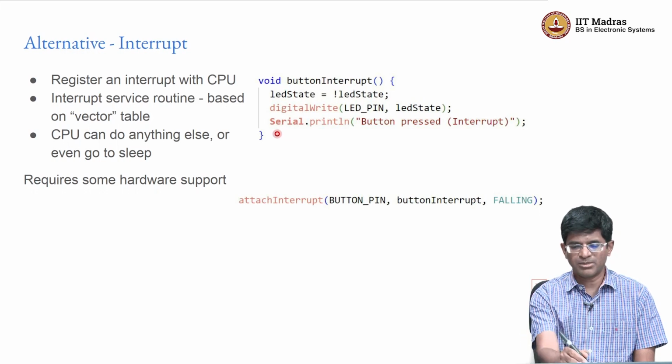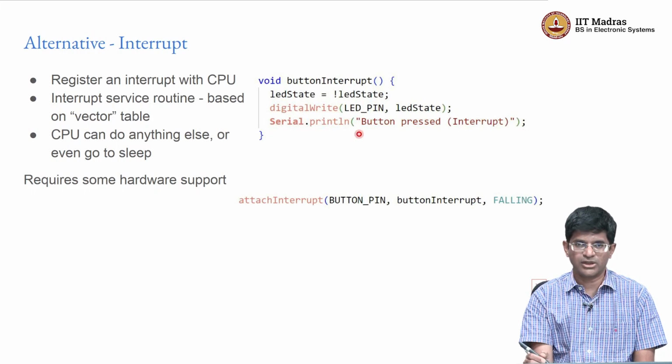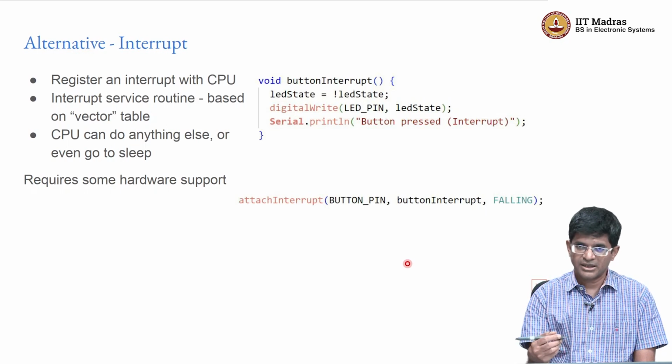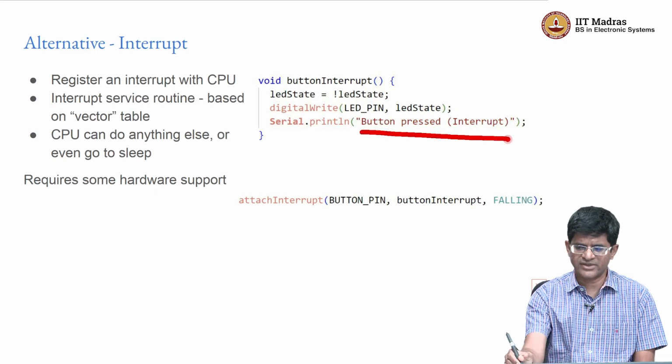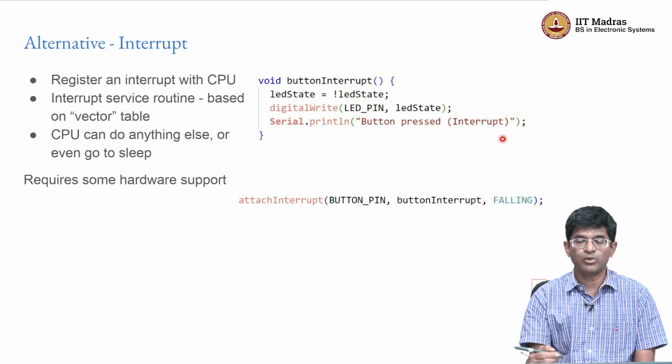Now think about what happens when you actually use a serial port in order to output data. If I have a serial port operating at 9600 bits per second, it means that for 1 byte, where I need to have a start bit, 8 bits and a stop bit, I will take roughly 1 millisecond to transfer 1 byte of information. And a string like this, which is roughly around 20 characters or so, is going to take up 20 milliseconds just to transfer data.